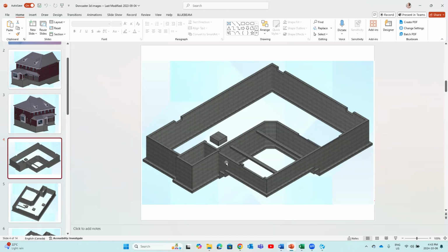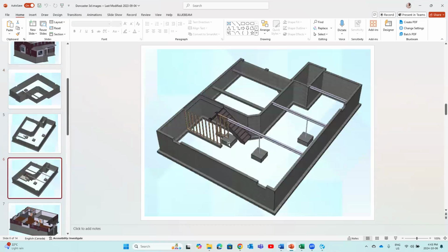Now you see this foundation wall along the garage. This is the garage, and there is a foundation wall along the garage. See, this foundation wall is shorter than the basement foundation. And also we can see we have partition wall footing, we have 3 column footings, and we have grade beams there. So that means when we excavate the basement, the shape we are going to excavate is this. That's a big hole we need to dig. Then we dig a trench along here. And also we need to think about column footing pits as well. This is how you can visualize it in 3D.